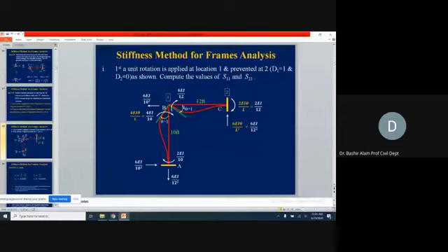If you see here, at 1 we are giving this clockwise rotation. If you see how the rotation is measured, starting from the original member to the deflected form. This down one curve is the deflected form, and this green line is tangent to this deflected shape. So theta equal to 1 is actually this rotation, and the sense of this rotation is clockwise.